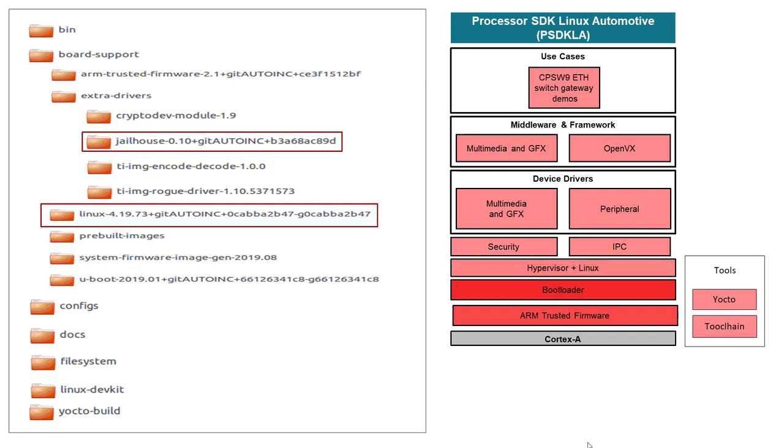Prosser SDK Linux package also includes a static partitioning hypervisor in the form of Jailhouse. This can be used to partition the system into independent domains that can then be mapped and used from independent virtual machine instances. The Prosser SDK includes an illustration of one such configuration running two virtual machine instances, both the instances actually running Linux as an operating system.